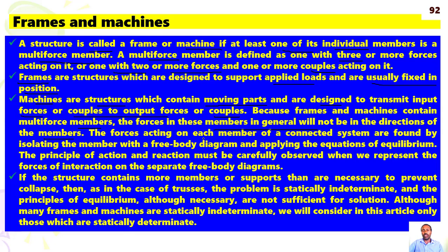The forces acting in each member of a connected system are found by isolating the member with a free body diagram and applying the equations of equilibrium. The principle of action and reaction must be carefully observed when we represent the forces of interaction on separate free body diagrams. If the structure contains more members or supports than are necessary to prevent collapse, then, as in the case of a truss, the problem is statically indeterminate. Clear? The equations of equilibrium are necessary but not sufficient.